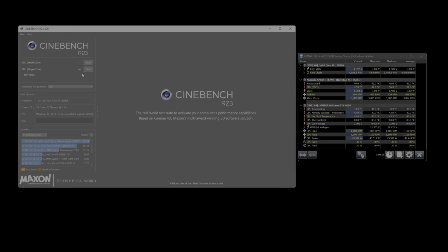Okay, so I'm just going to run a single pass on Cinebench to see what kind of results I'm getting from my processor. What I'm looking at is Core VID and vCore, also CPU temperature. As you see, just booting up the system, I reached a maximum of 56, but running 47C here. So I'm going to start one pass running on Cinebench.